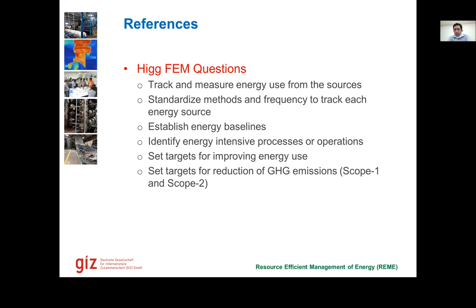Number one, track and measure energy use, standardize methods and frequency to track each energy source, establish energy baselines, identify energy intensive processes or operations, set targets for improving energy use, and set targets for reduction of greenhouse gas emissions in scope 1 and scope 2.